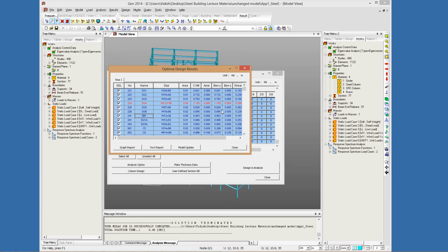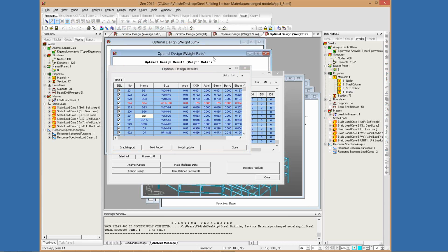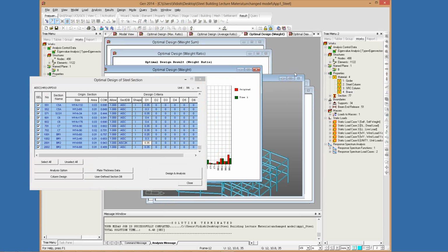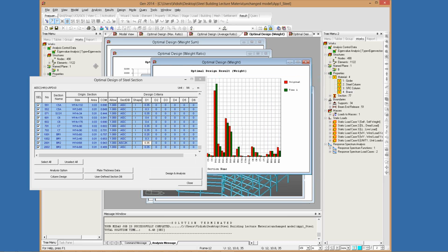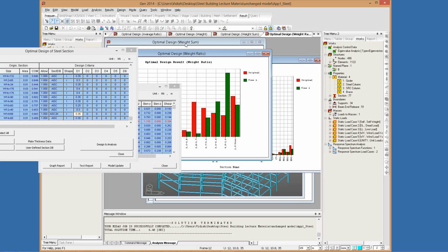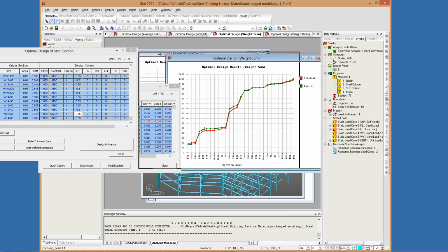If you want a graphical update, so let me show you the graphical update of it. So as you can see, for some it reduces, but for some it increases because some sections are failing, so the section weight needed to be increased as well. But if most of your sections are passing, if you change the sections once they pass in the second iteration, as you can see for the green lines to the right, the section weight is also reduced. So you can also compare this over here so that the final section weight can be reduced.